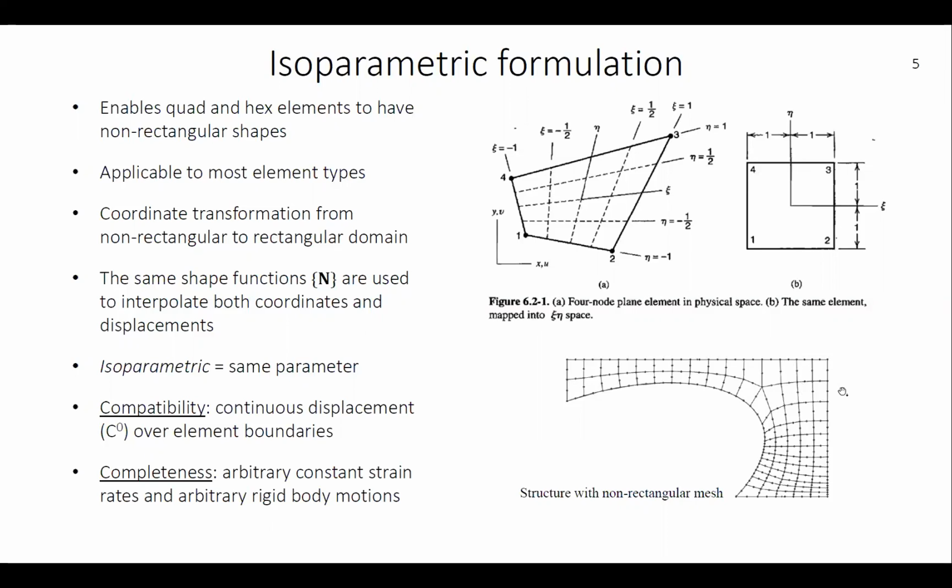And one way of treating that is to extrapolate the stresses to the nodal points and then take an average value for each of the nodal points. So I will show that concept later on. And you will also need to use that in part of exercise A with the cantilever beam.